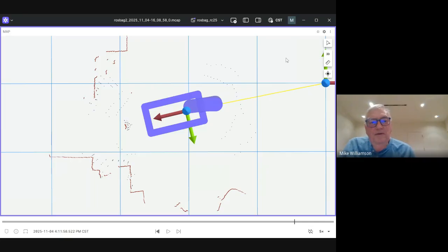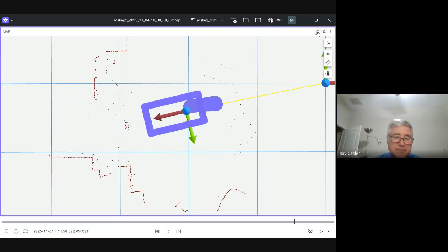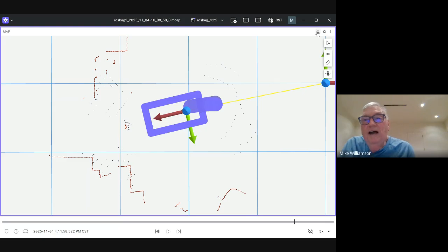So that's the, I can't remember, VL53L8, I think, sensor, which is supposed to be, again, a higher ambient light sensor. Better for outdoors. A little more expensive than the L5s, which are all of my sensors here. I have 3 of them, so it gives me about 130 degrees. Each of them has 45 degrees, and so I put them all together, and I got a 130 degree range.